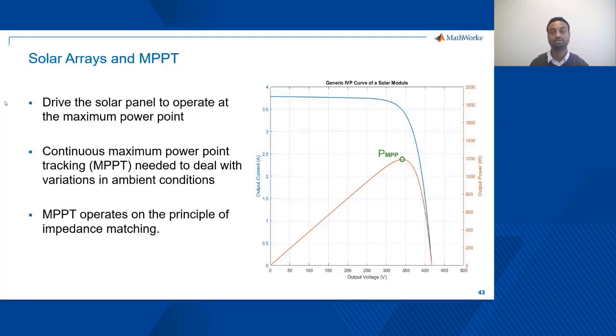The reason why we have those two additional components, the MPPT and the power converter connected to the solar cell, is because of its special characteristics captured in this I-V curve. The I-V curve, which shows the output voltage versus the output current and the output power, shows that the current deteriorates sharply after a certain threshold voltage. That means that the power gradually increases towards a higher maximum point and then also gradually declines.